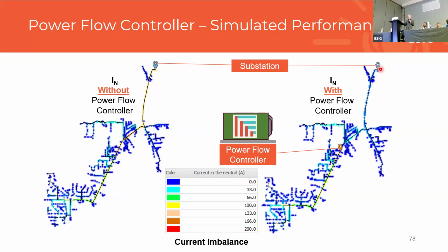And that's a good thing to note here, that the device doesn't get overloaded per se. It will correct up to its highest rating and then it will stop. So if you have 150 amps of neutral current on there, it's going to clear up 130 and it's just going to leave the rest on the system because it's not rated to do that. The other thing that's really showing up here is that it is shunt connected. So below it, the imbalance exists, but above it, you have kind of corrected for that imbalance.